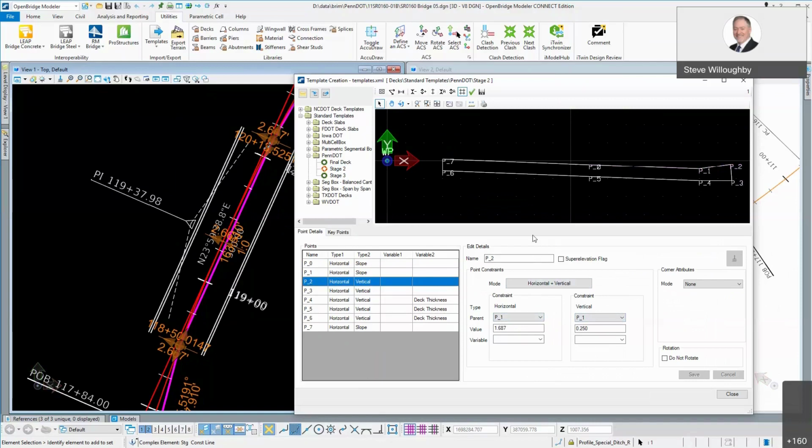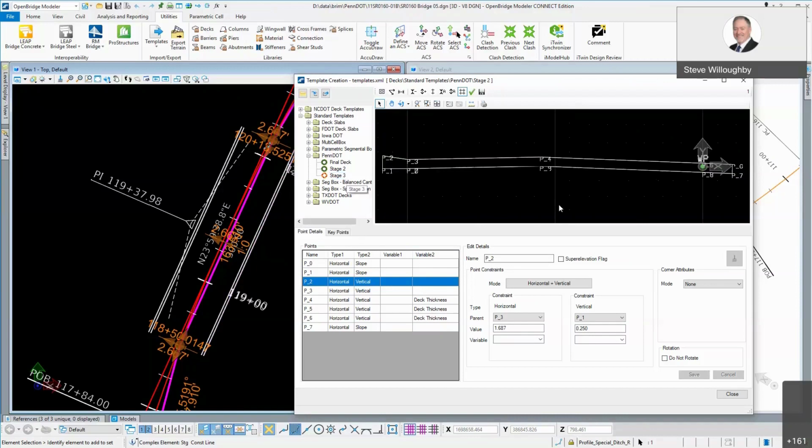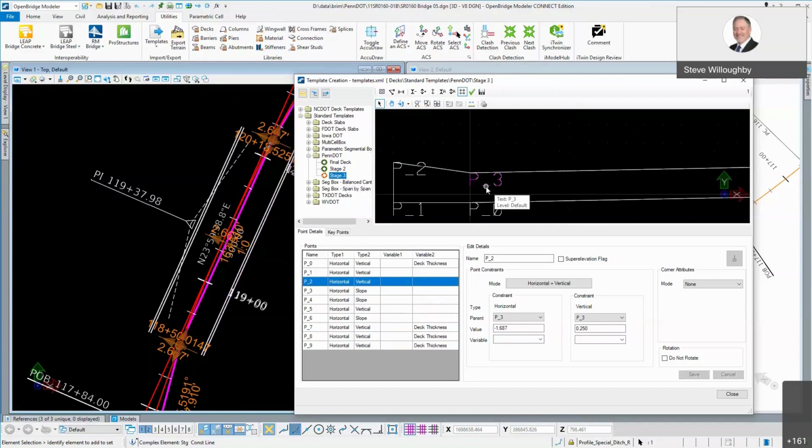And what that does for us, by me setting 0.1 and making it a tangent line, that forces the right edge of deck to be now parallel to this line. So I didn't really have to set both of these. I thought I was going to have to set both 0.1 and 2, but it turned out, by virtue of how I define my deck template, I really only had to define one of them to get this to work out well. And same sort of thing on the left side as well here. In this case, 0.3 will follow this line right here, and 0.2 in this case is a fixed distance from 0.3, both horizontally and vertically, and that will force the 0.2 to move quite nicely as well.